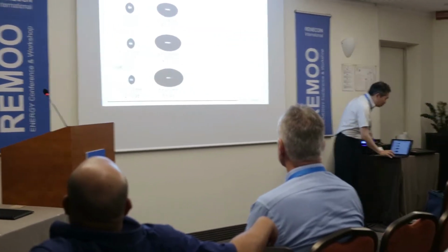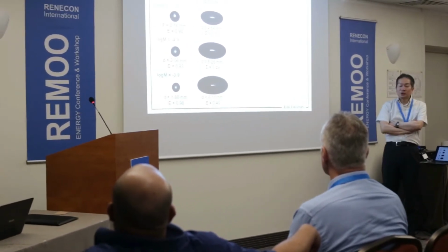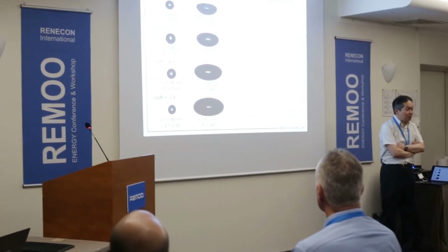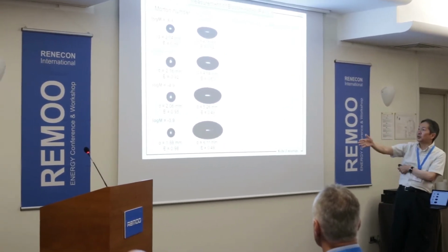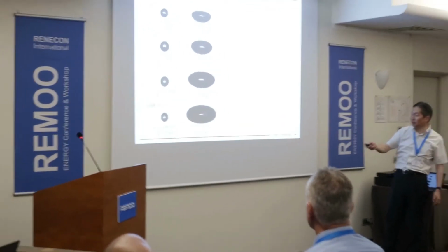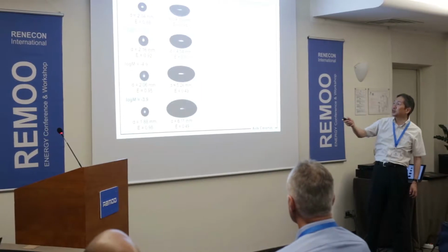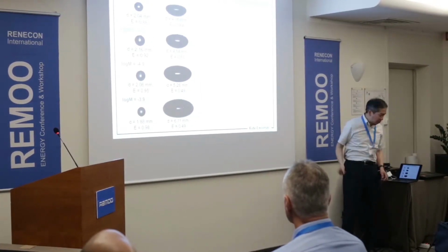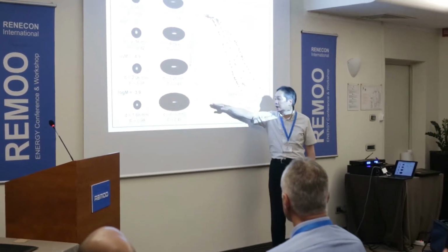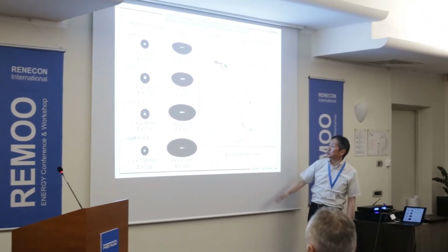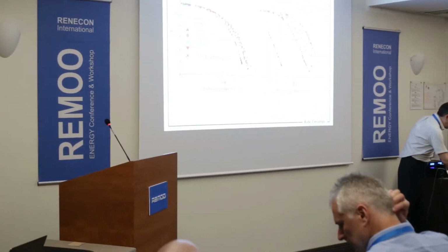We restarted to measure the bubble shapes themselves recently, because there are few reliable models for bubble shapes. And we measured the bubble shapes for different Morton number systems like this, very, very viscous systems from -4 to -7, and obtained this kind of aspect ratio data against the bubble diameter. As you see, as the bubble diameter increases, the deformation becomes large.